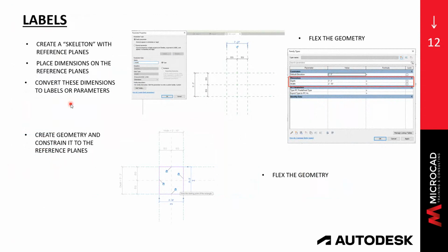And then, best practices when you're going to create the family. Before I create the family, there is a whole bunch of questions that I ask myself. The first question is, how intelligent or how parametric do I need my family to be? And again, parameters, intelligence: do I need my family to stretch? Do I have a family that has the same geometry, but I need different types of that same geometry? I need to have all those things very clear in my head before I start creating a family.